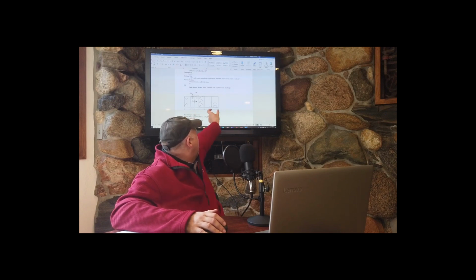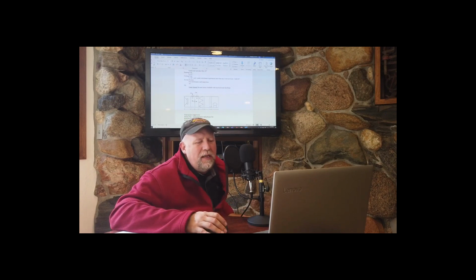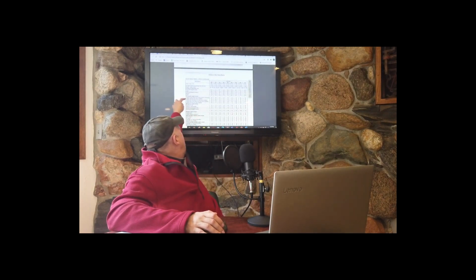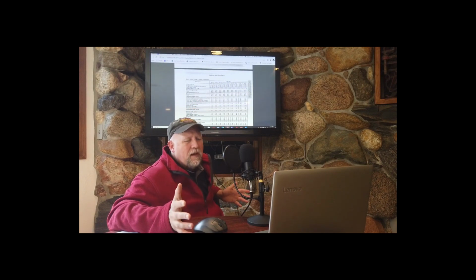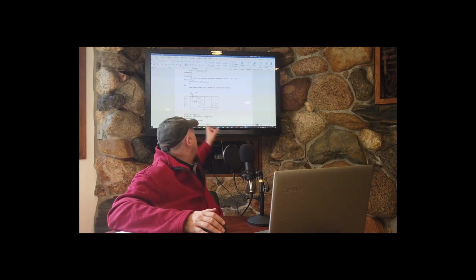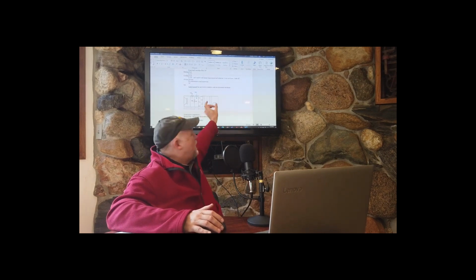All right. Also, let's take a look at the supply fan. Rather than a plenum fan for the supply fan, we're going to use the largest housed fan and motor available with top horizontal discharge. Once again, which fan we pick is kind of beyond the scope of this class. Just know it is a 92-inch long fan section. So back here, for the supply fan, 92 inches.